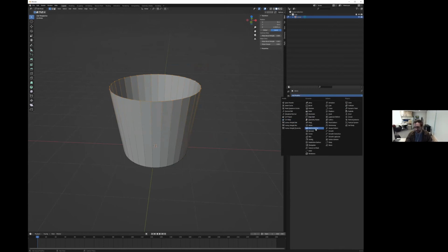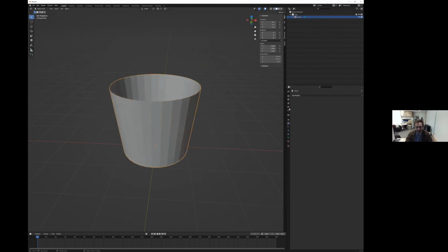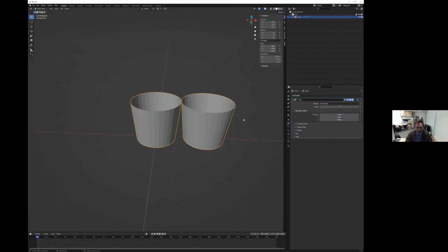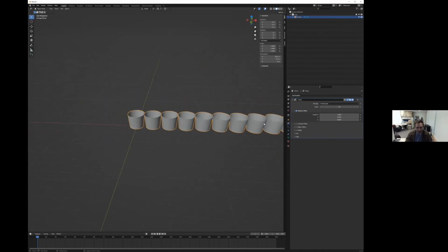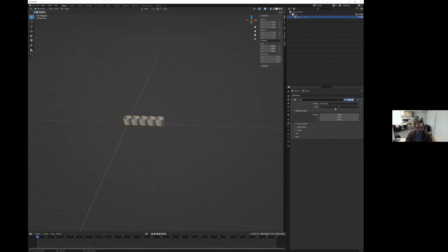Things like mirroring. So you can work on one object and you can mirror what you're doing on the right side, on the left side. Or Boolean. You have one object intersecting the other, and then you choose which object you want to bool, and then it will pretty much make an intersection point, or it would get rid of some geometry that's overlapping. Or even array. If I wanted a bunch of these, you can have an array modifier that expands, so you don't need to duplicate.